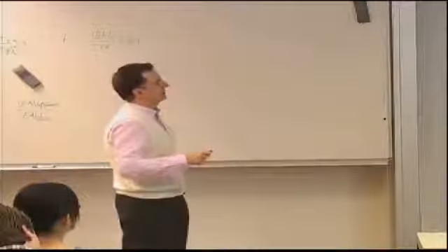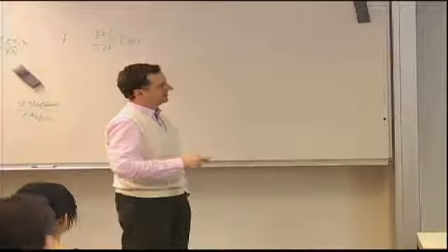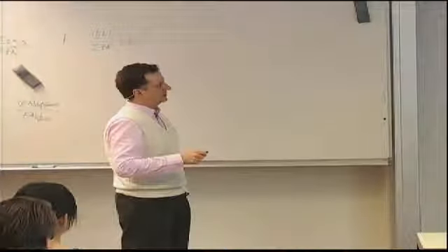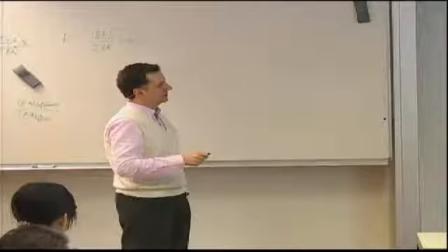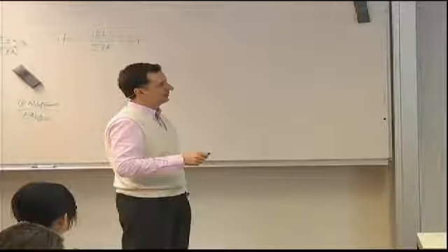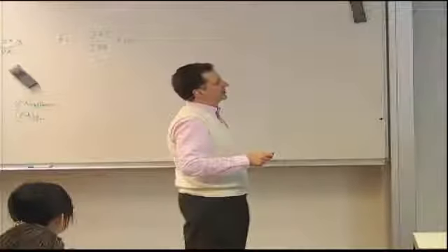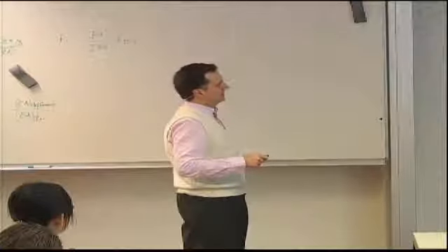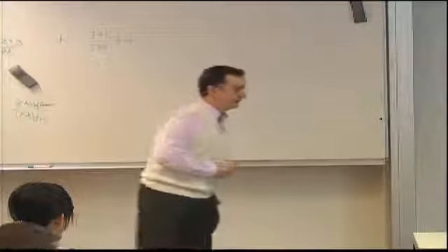That condition that it's zero displacement at x equals 0 gives us C0 plus C3 equals 0. The corresponding condition at x equals s will give us this whole mess that involves C0, C1 times s. It's evaluated at x equals s, so whenever there was an x before, there's an s now. The bending moment at x equals 0 gives us this condition, and the bending moment at x equals s equals 0 gives us this condition.